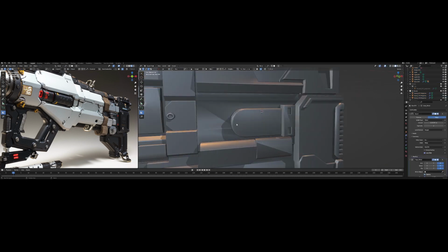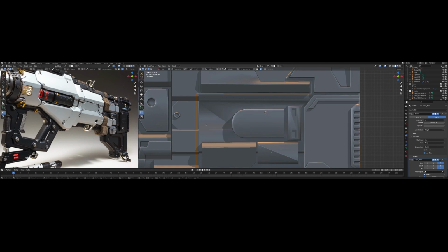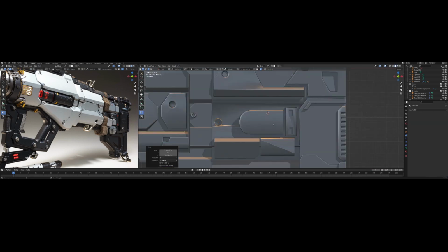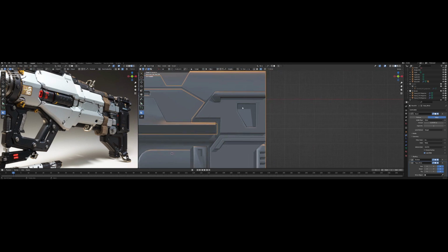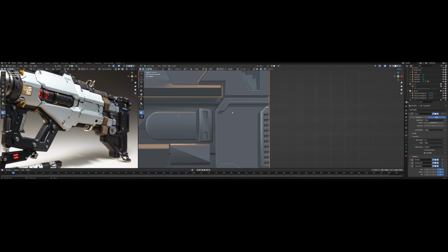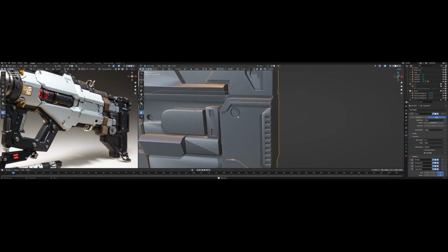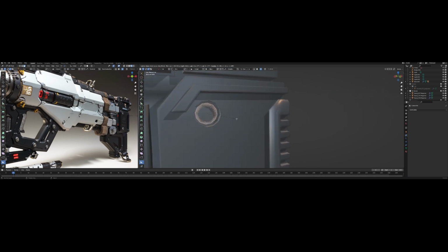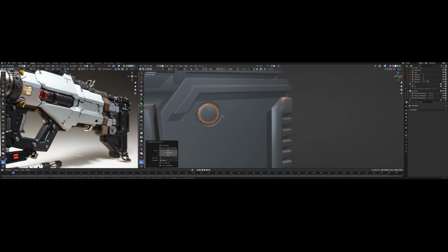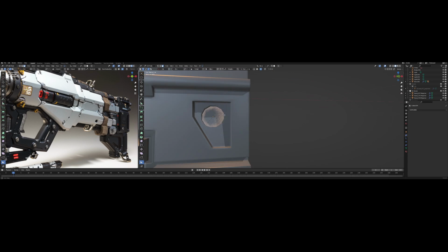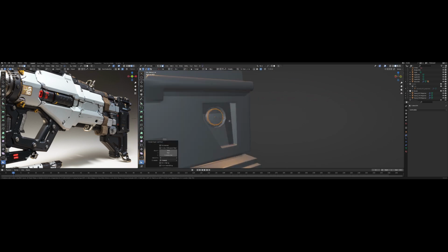Another thing I want to say, especially for those areas, as we can see there have already been a lot of holes and curved parts dug inside it. If you just want to make another joint boolean on it, you'd better make the interior parts extended to the innermost part of the main part.